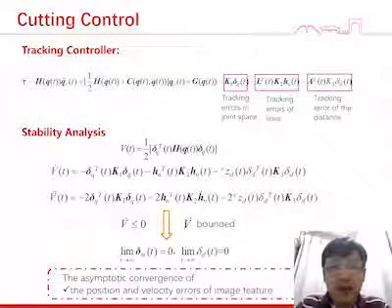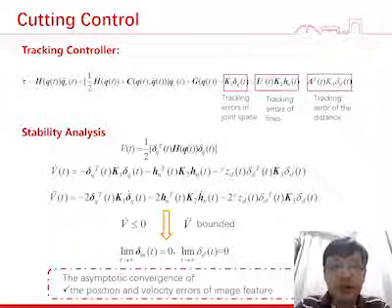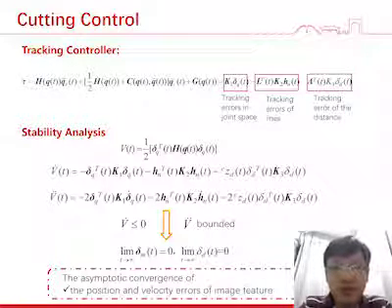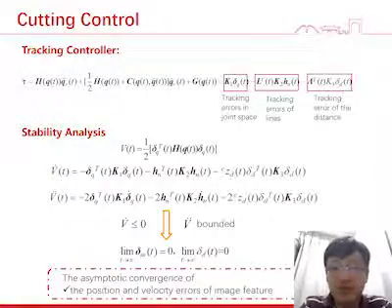According to the target surface on the image plane, the robot is manipulated to control the knife's projection to track it in real time. Video feedback and joint feedback are both fed into the proposed controller, and it can be proved by the analysis that the position and velocity error of the selected visual feature will asymptotically converge to zero.